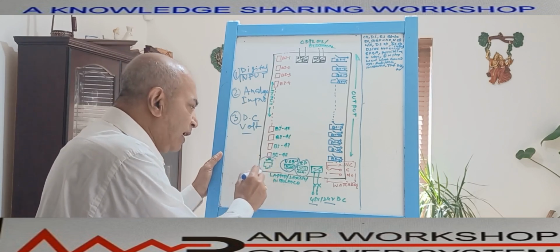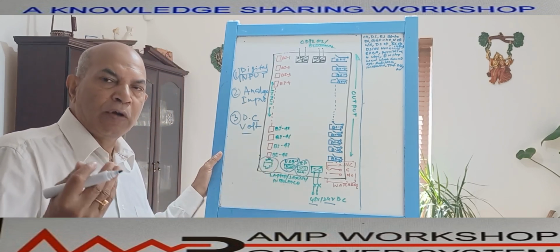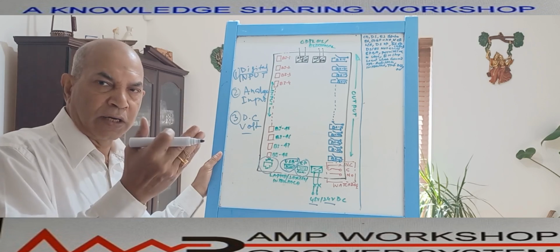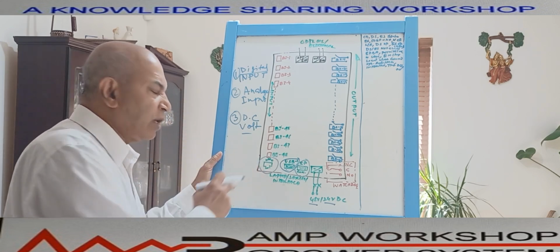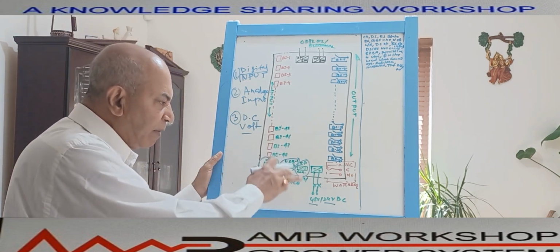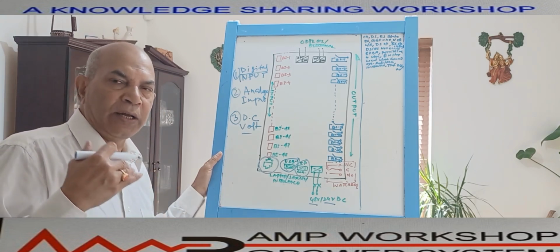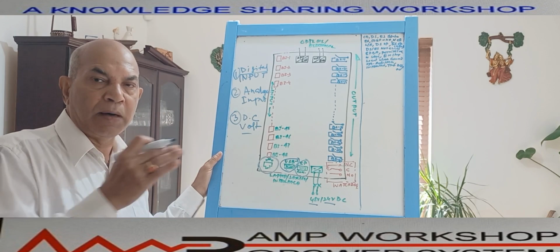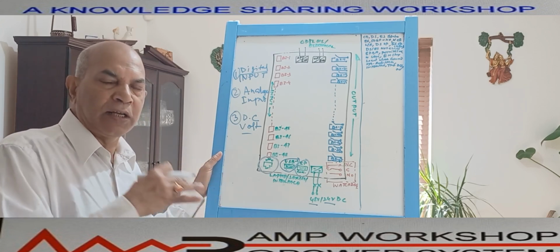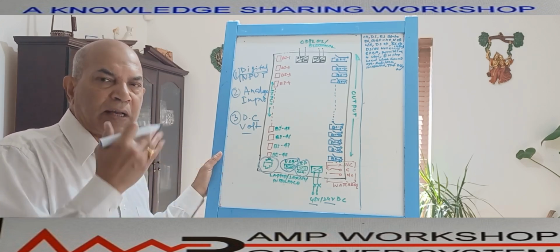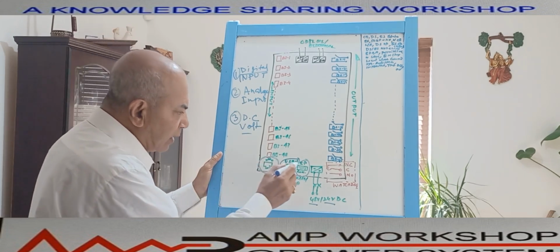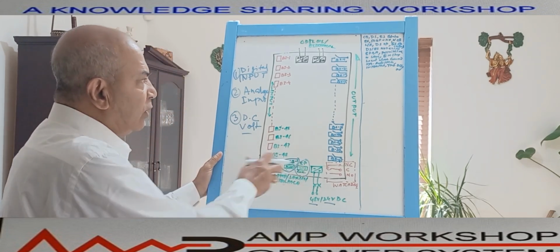Then this relay has an Ethernet port which we can use for connecting directly to the network. If we want to connect this relay directly to the communication network, we can use it through the Ethernet switch. This is the Ethernet port to connect the Ethernet cable. You can also connect a parallel port if you want parallel path data to be communicated. In that case we have to order accordingly. The parallel port has a higher communication capability, and that also we can incorporate as per requirement. So various digital devices we can connect through this interface.